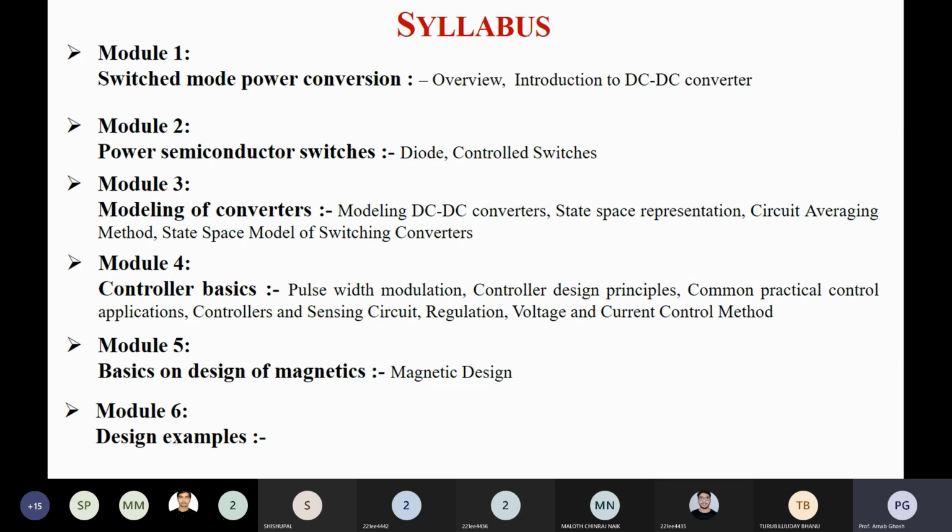So that's why you have to use this for high frequency applications. For that, the magnetic design is very important: which type of components you are using. Normally we are using a ferrite core, instead of a ferromagnetic core.